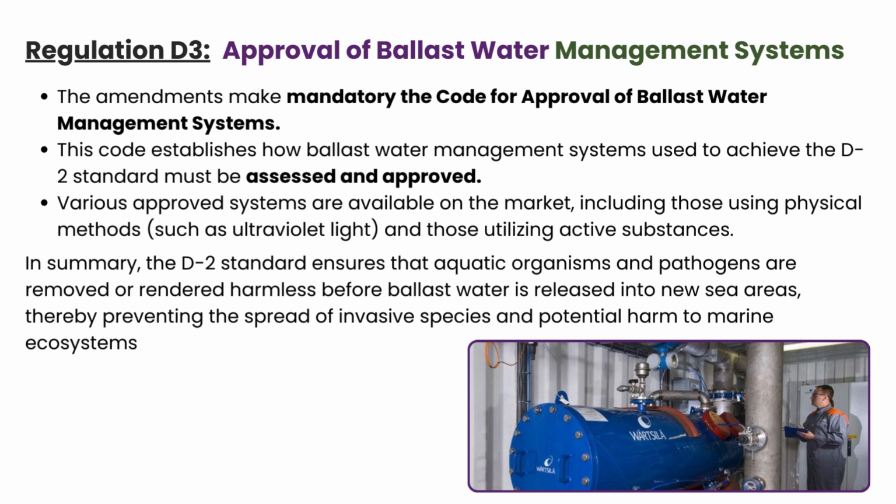Various approved systems are available in the market, including those using physical methods and those using active substances. We will go into much detail on that. In summary, D2 standards ensure that aquatic organisms and pathogens are removed or rendered harmless before ballast water is released from one ocean to another, thereby preventing the spread of invasive species and potential harm to the marine ecosystem.